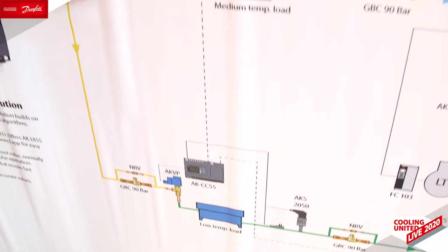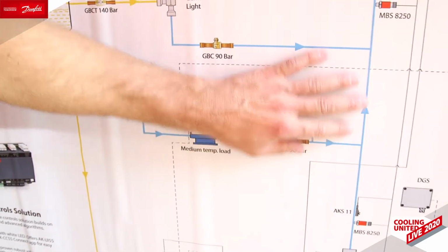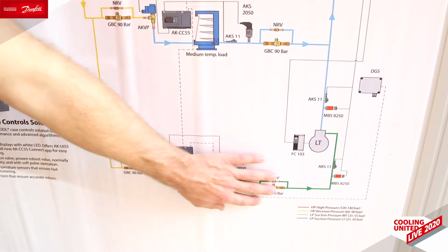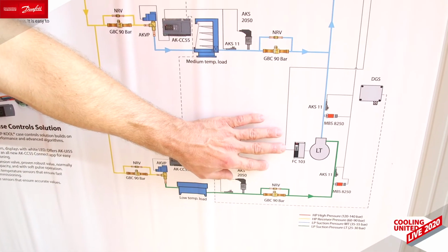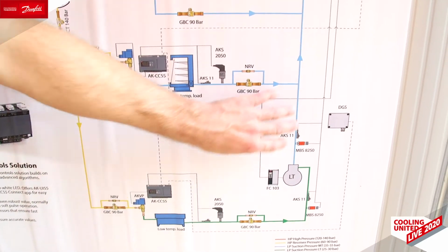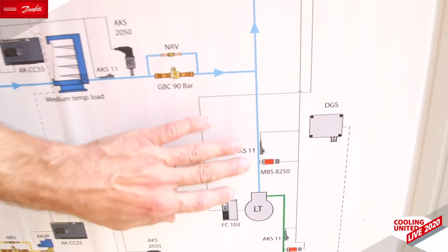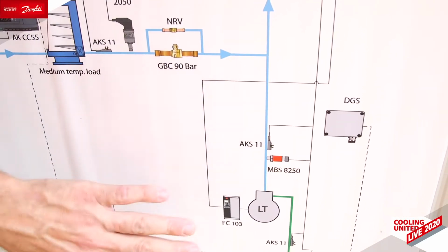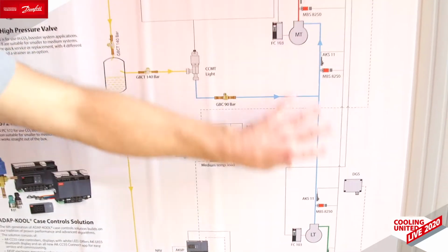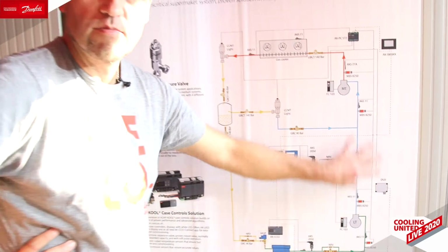And that closes the loop with the MT gas coming back to the MT compressor and the LT gas coming to the LT compressors. And the LT compressor lifts the gas to the evaporating pressure of the MT compressors, and in this way we talk about a booster pack, and hence the name, a simple booster system.